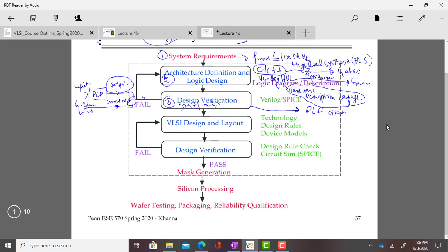The golden results are the results which you know are correct. So for example, if this is a 3-bit input, the verifier will apply all 2 power 3 inputs, which are 8. It will apply all the 8 inputs to this circuit and will check if the results are correct or not.